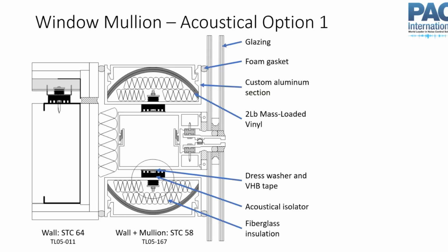Chips says, don't forget covering the couplings of the electrical boxes. I don't know if Chips means just if they're touching back to back, or between the electrical box and the drywall. But either way, don't do either of those. You want to make sure that they're separate. They don't touch each other.